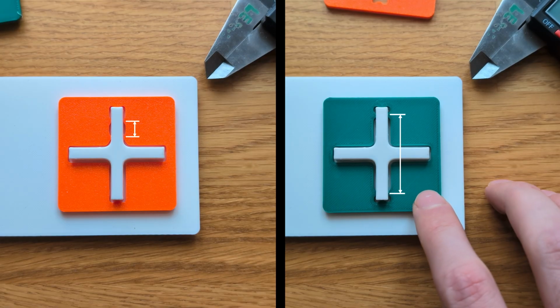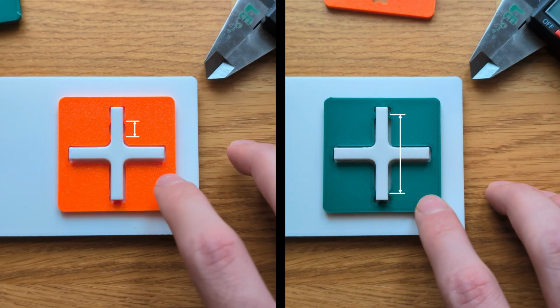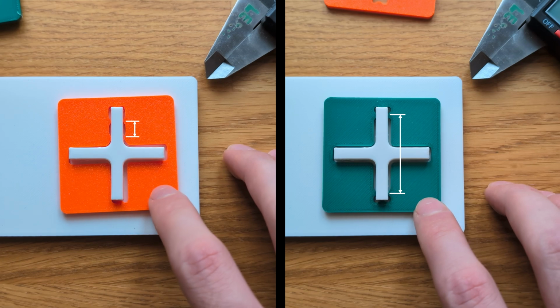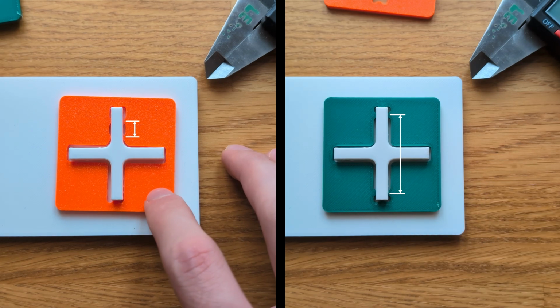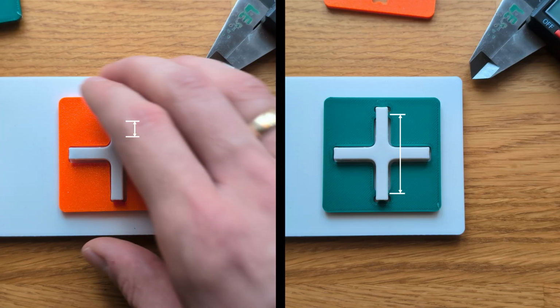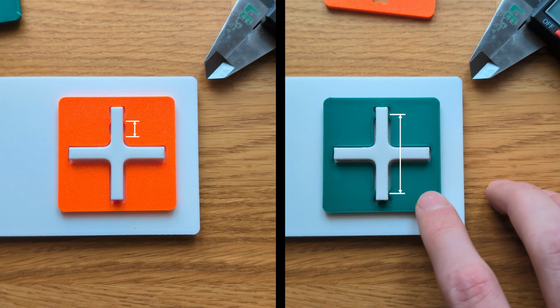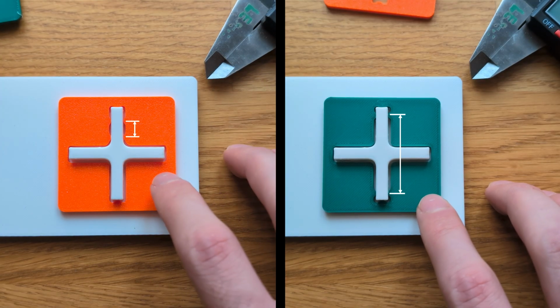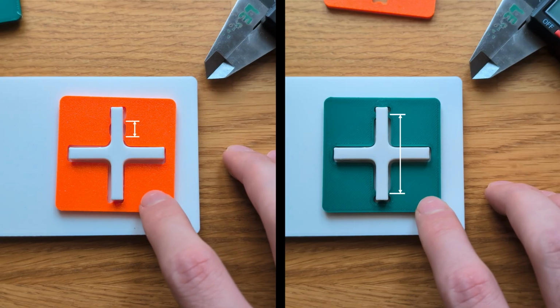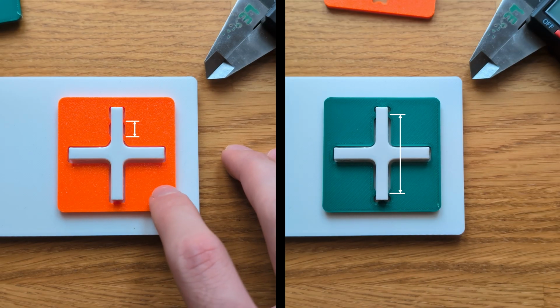In the example from the introduction, you can see the difference in performance between 2 different designs. The only difference is the distance between the constraints. Same clearances. So remember how proportions in 2D stacks can work to your advantage. Your design has the potential to be more precise without tightening tolerances and increasing cost.